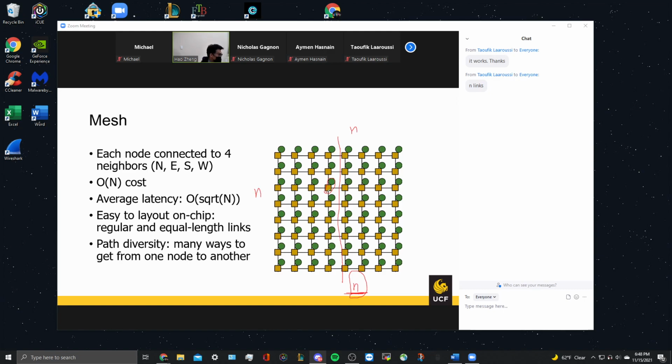Just to guess, bidirectional for this one here, is that 8 if you're cutting it in half? If you count the number of lines you're slicing through. Yes, if it's bidirectional. So for this one, actually, it's just bidirectional, because you have 2 ways to go. Each core has 4 ways to select, and this one also has 4 ways to go. So the combination of these 2 routers will naturally perform a bidirectional link between these 2 pairs.